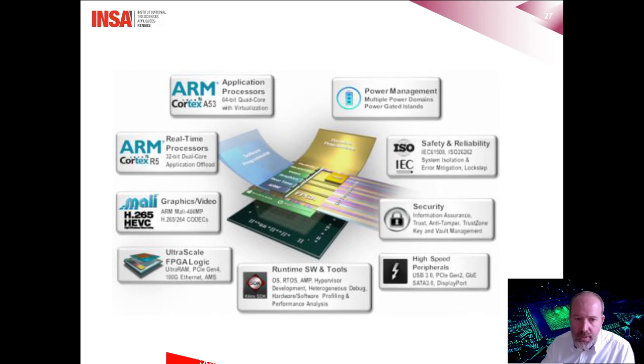Other specific processors such as graphics processors are also included inside the FPGA. And next to the processor, we find a logic area which finally contains the matrix of logic cells as described previously. This makes it possible for designers to implement hardware accelerators to enhance the processor's performance.